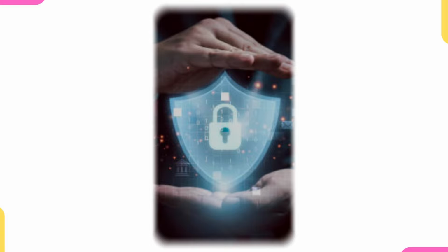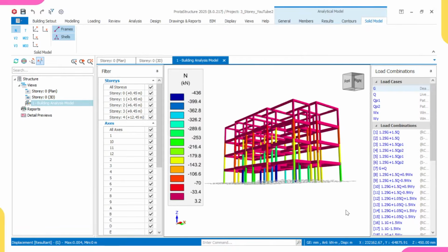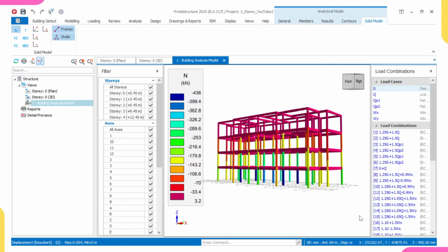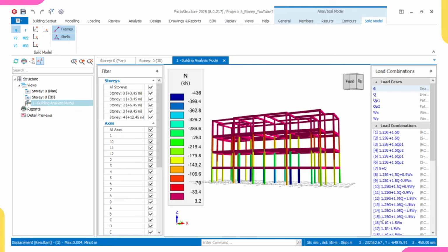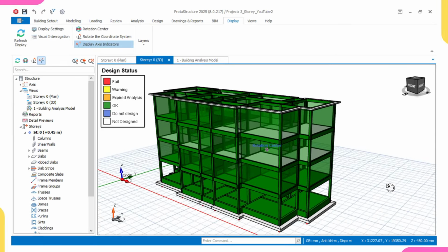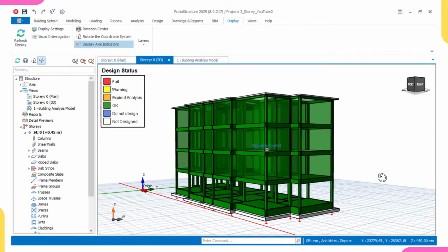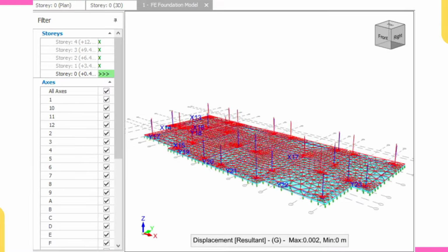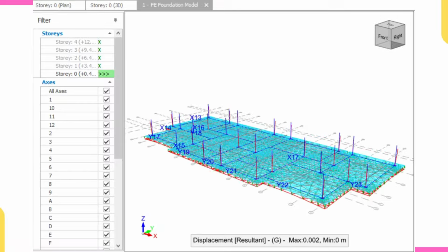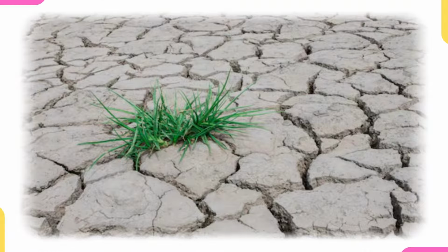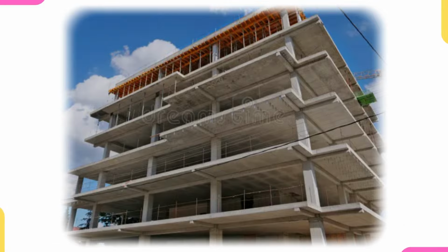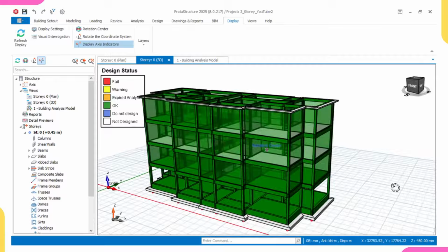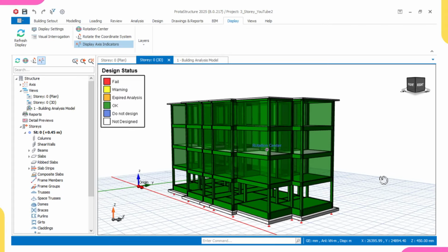From there, we go into analysis and design, where we carefully analyze the forces acting on every structural member, that is columns, beams, and slab, and then provide reinforcement to counter those forces, which is design. Then next, we move into modeling and design of this beam raft foundation, where I explain everything you need to know, the reason why we chose this beam raft foundation, which is as a result of the weak soil, knowing fully well that pad-based footing will not be able to spread the load coming from this structure to the soil. I will show you how to perfectly design a beam raft foundation and the governing principles behind that.